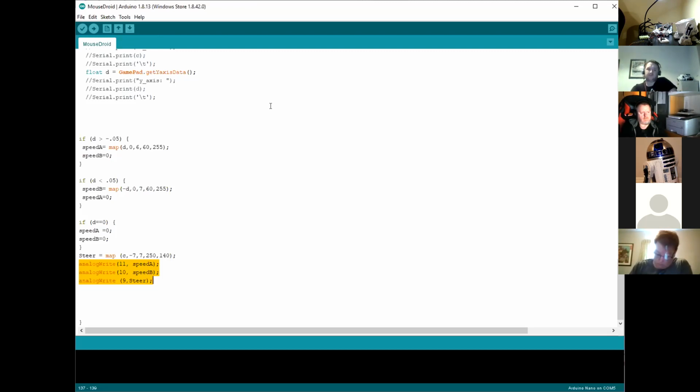Yeah, and what I'm using here is analog write, which is literally directly controlling the pin on the Arduino. If I was to use a library, like the servo library, for example, you input your output between 0 and 180, which is the angle of the servo, but it'll actually tell you in the library. If you're using a library for a speed controller, like Sabertooth, for example, that may say 0 to 1025. So each library and each hardware will have its own spec. It just requires digging around a little bit to look at those.